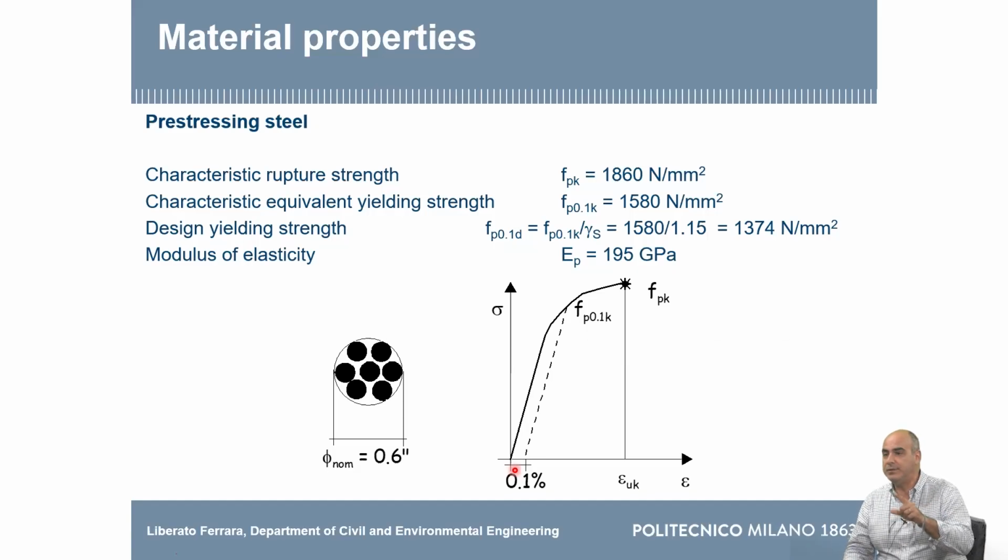And it doesn't give you just a sheet of paper written, it gives you certificates of an official lab. In our lab, in our university, we make tests to certify these tendons. And we make tests in the lab, but for steel, our personnel also goes to the factories worldwide, because you have to inspect the production. So every now and then, periodically, you go there and say, okay, let's pick up 2 bars from that lot and let's test them and so on. So you regularly certify that.